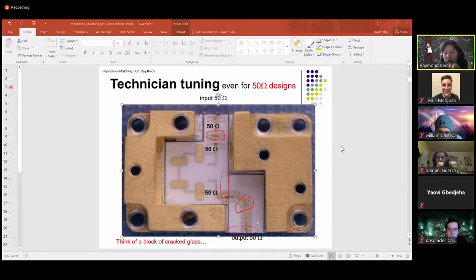This one is very obvious because this is the bend. When the transmission line bends, this portion, the impedance also changes a little bit. So putting a ribbon here makes sense. Putting ribbon here, that's close to where the junction is. That makes sense. We'll talk about what that means, mathematically or in a transmission line model, exactly what does that mean? Okay. So this ribbon here is to match the impedance. It's one of the techniques that we're going to talk about for impedance matching.